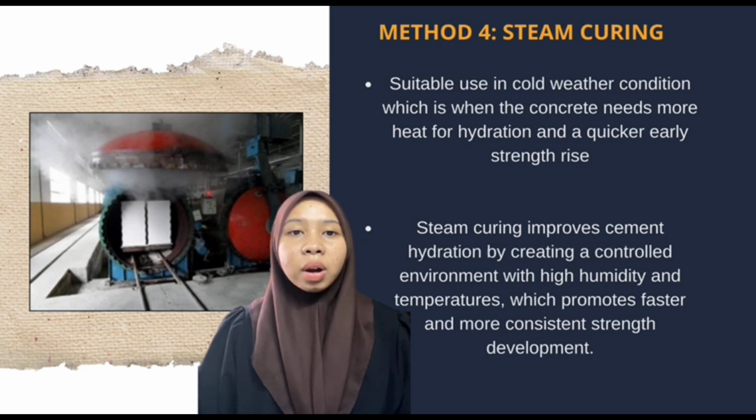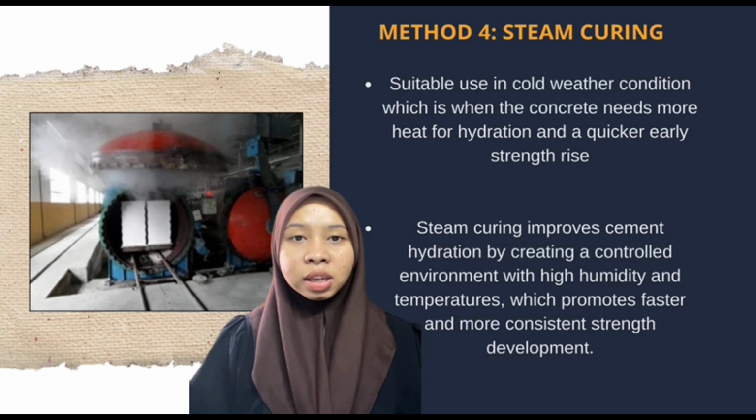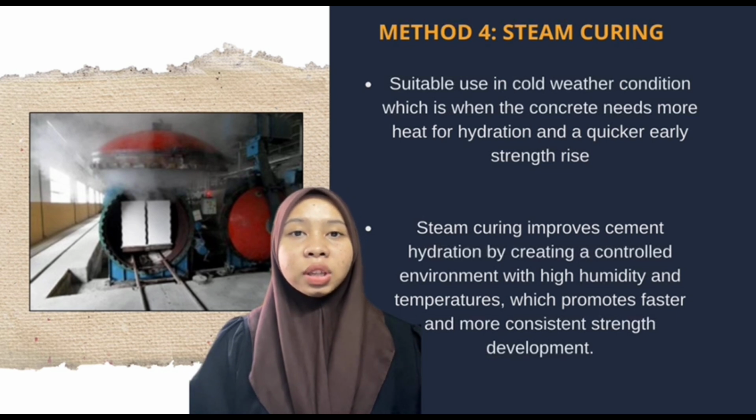The precast members are kept within chambers during large-scale concrete production at a factory. The process of this method is quick and is mostly utilized for large-scale manufacture of concrete members. By maintaining an ideal temperature, the steam curing method may achieve the 28-day standard curing strength in just 3 days. There is also high pressure steam curing, also known as autoclaving.